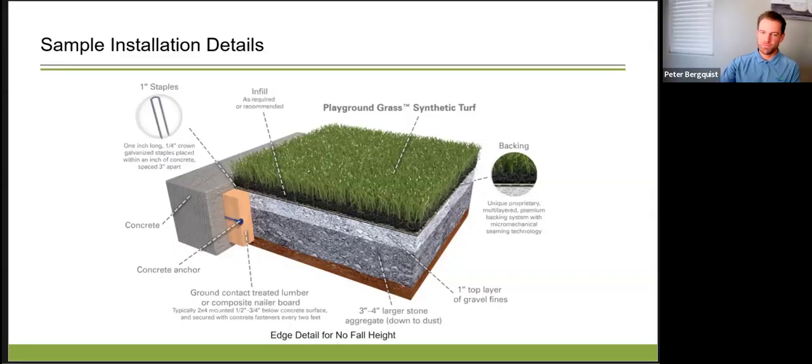Why is drainage important? At least here in Las Vegas, it doesn't rain often, but rainfall has a cumulative effect. Water erosion actually shaped the Vegas Valley. So erosion of the subbase or type 2 base will happen, just a matter of when, depending on site conditions. So I say all that to say that it's important to specify the base material.